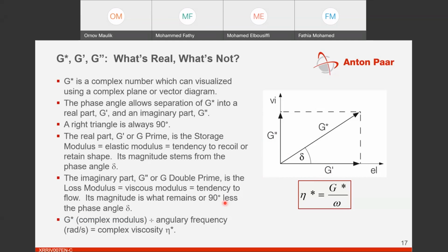As the formula suggests, tan delta, that is G double prime divided by G prime, primarily gives information about the viscous behavior of any particular material. So most of the time when you are doing experiments where you are expecting some sort of phase transition, like a curing experiment, or any type of time dependent study, this tan delta factor would actually tell you what changes are happening in the structure. So that is also something very important to characterize.